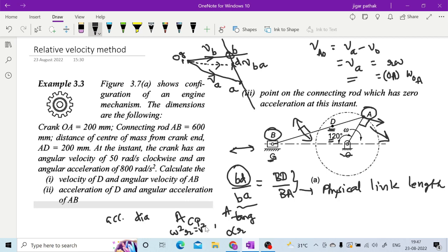Linear velocity square upon r. And linear velocities of all the links are with you from this velocity diagram now, so you can calculate the centripetal acceleration of almost all the components from this linear velocity. You know the link length, so you can calculate this. And angular acceleration is given for some of the components, so you can also calculate the tangential component for some of the links because angular acceleration is provided.